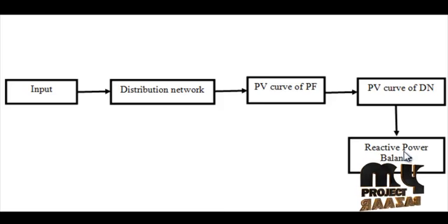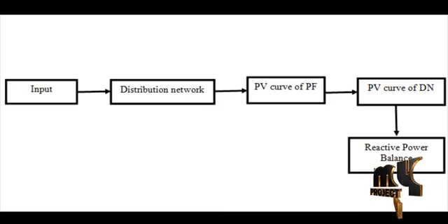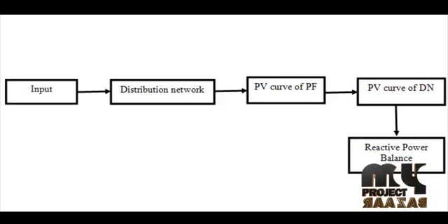Assuming that power grid voltage V0 is 1.1, grid reactive power voltage curves are drawn with various ratios of reactive power with respect to active power. The family of curves is drawn together with the load reactive power voltage curve. The load reactive power voltage characteristic is described by a quadratic curve. The curve characteristic parameters are as follows: the rated voltage Vn equals 1, the critical voltage VCR equals 0.75, the rated reactive power Qn equals 0.2, and the absolute value of dQ by dV in the left section is 2 times bigger than that in the right section.